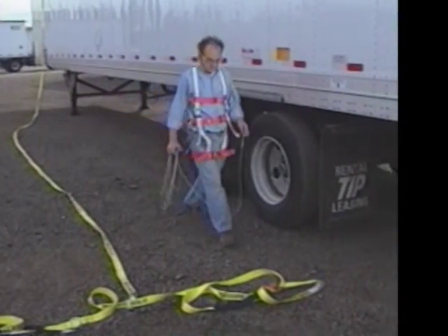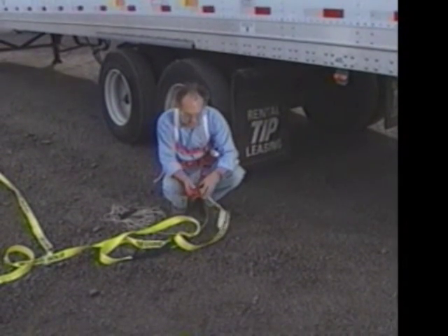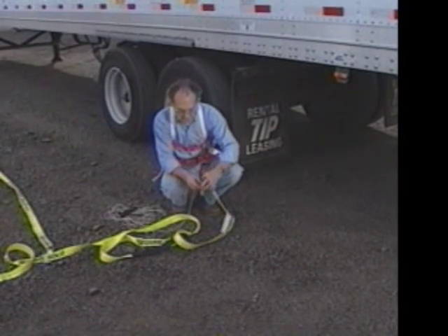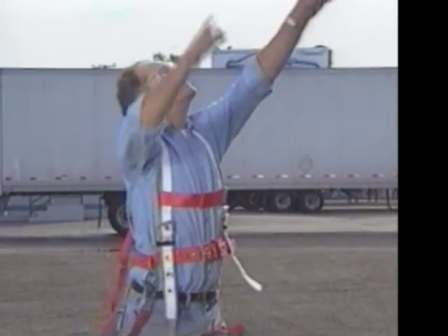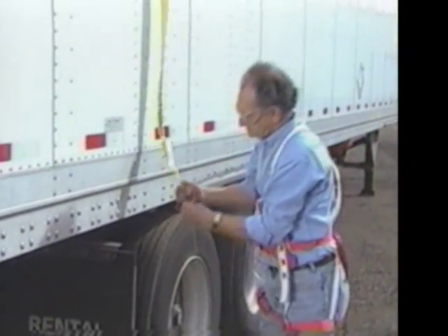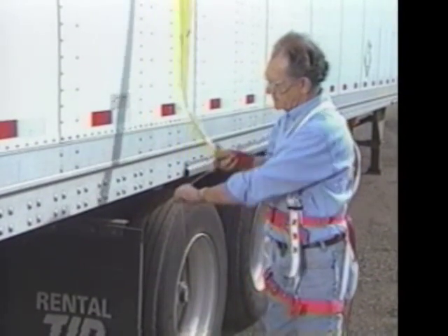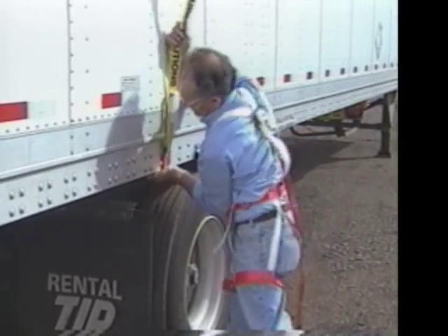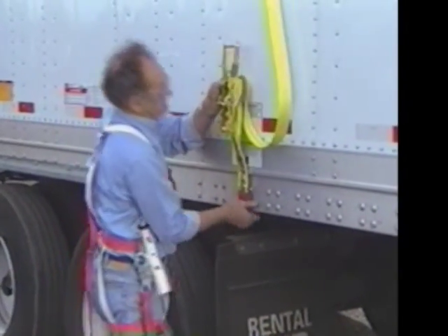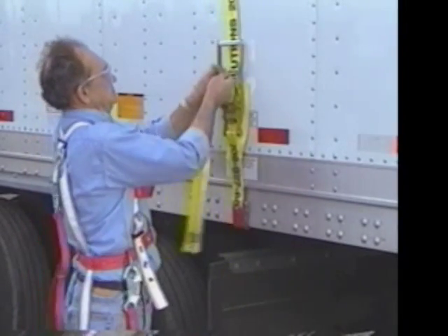Repeat the same procedure on the other end of the trailer. Attach the throw line. Check for people or obstacles. Throw the line over the trailer. Pull the cross strap over, making sure the center strap does not get tangled. Place the flat hook on the bottom rail. On the other side, place the flat hook on the bottom rail and operate the ratchet to tighten the cross strap into place.